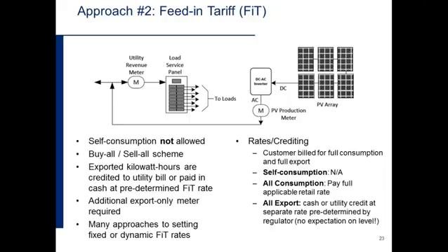So for a feed-in tariff, the customer continues to consume electricity as normal, paying the standard applicable rate for electricity. The PV system is not really wired behind the meter at all in this case. Rather, the power generated from the PV system is sent directly out to the grid, measured separately and credited separately. This is a proper buy-all, sell-all scheme, where the sell rate is customized and usually fixed for the lifetime of the asset.